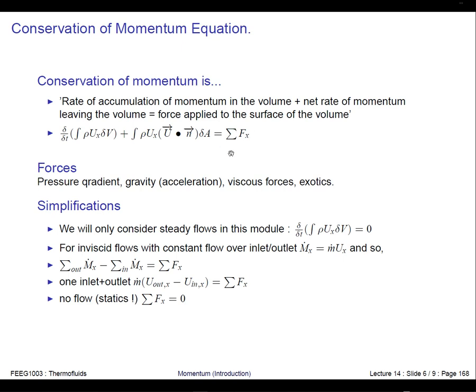The tricky bit for understanding how to solve problems is really where to put the control volume and how you apply your additional forces on the surface of your control volume. Okay, so these might be pressure forces. The best way to do this is using an example.